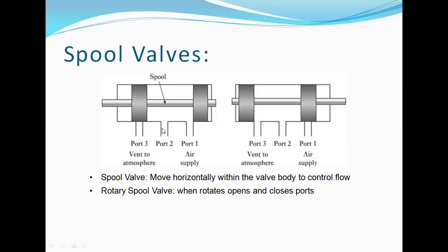In the retraction stroke, the pressurized air that entered the cylinder through port 2 is released, and port 3 is in open condition, the vent condition, so there will not be any back pressure. When the spool valve is moved towards the left side, port 1 is closed by the right end of the spool, and the left side is open. The pressurized air that entered the cylinder is sent back and released to the atmosphere through the vent. Towards the extreme left, the supply from the compressor stops, and the already entered pressurized air is retracted back, which is considered the return stroke. The returned air is released directly through the vent to the atmosphere.